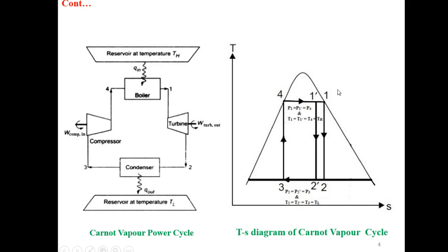So it will not make the Carnot cycle. So there is a limitation for point 1. It can be only the dry saturated point. It cannot be a superheated point.